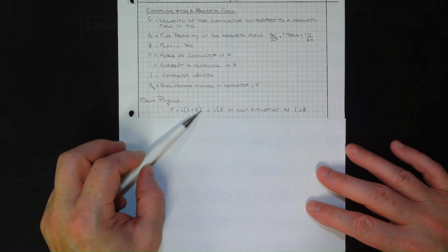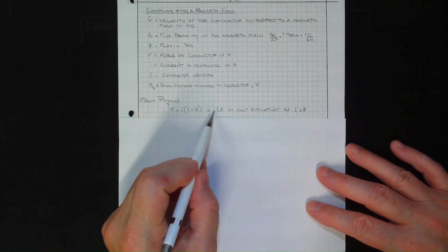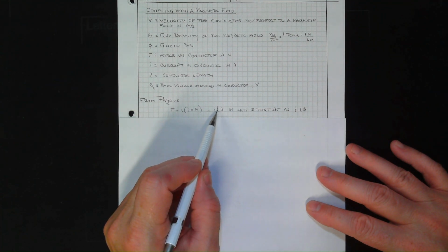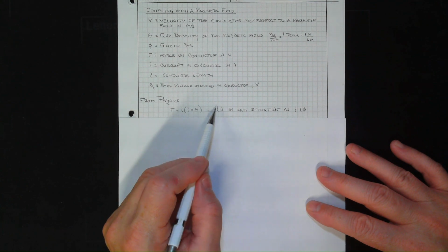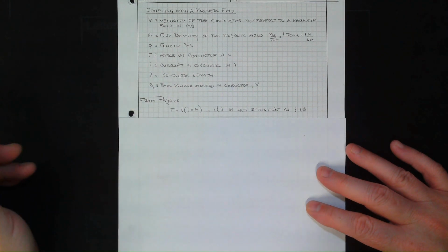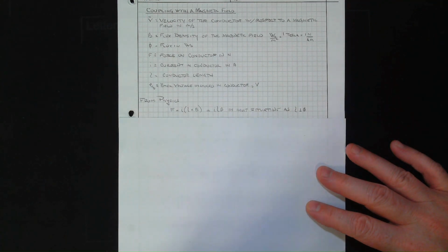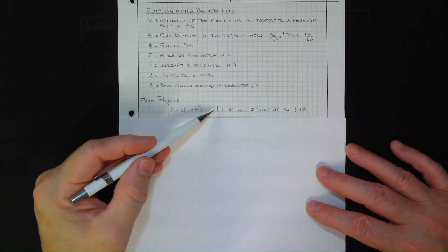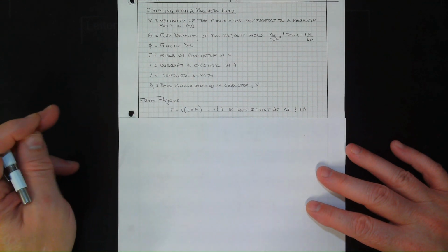These things are generally set up perpendicular, such that this is a normal situation set up to be current times conductor length times the magnetic field. And note, as your windings are set up, you could have many windings combining to create tremendously large lengths of conductor within the magnetic field.